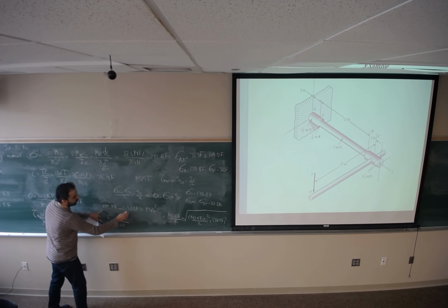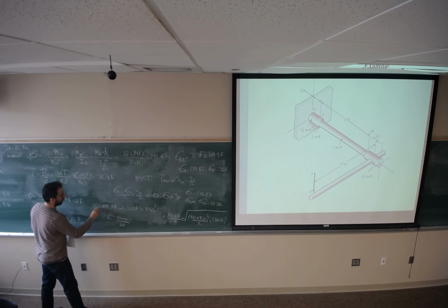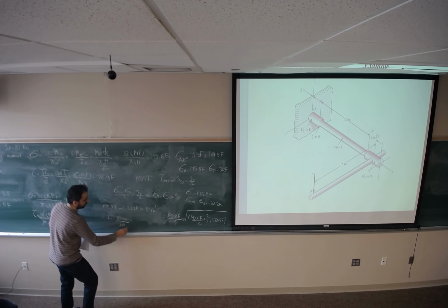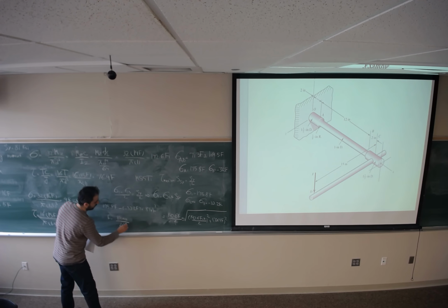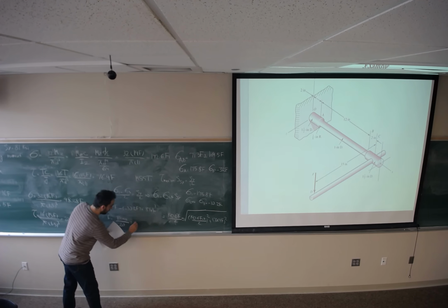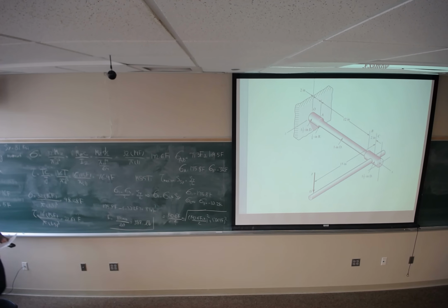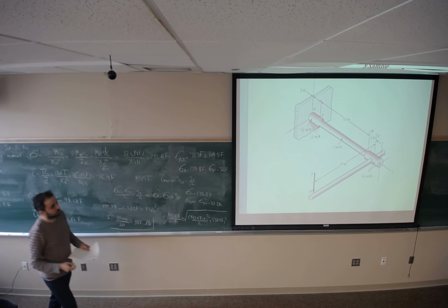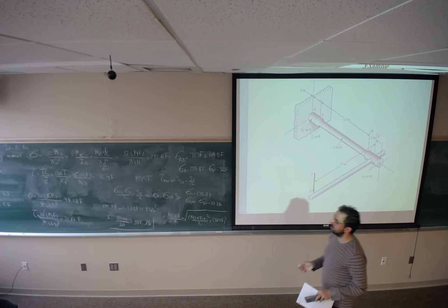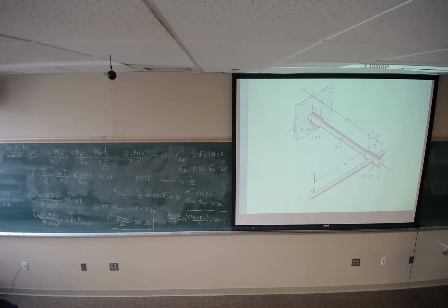The summation of these two is going to be 209 times F, so I will get 388 pounds. So based on maximum shear stress theory, the maximum force that you are allowed is 388 pounds.